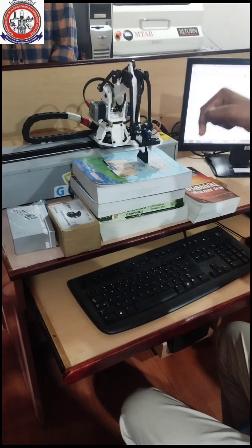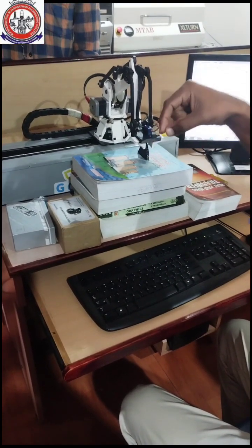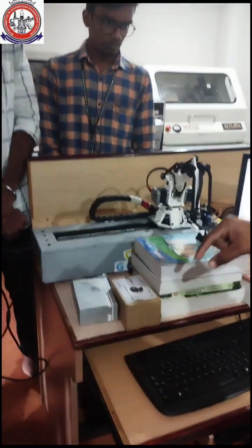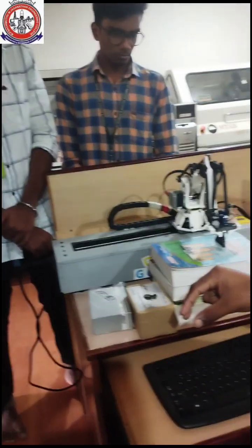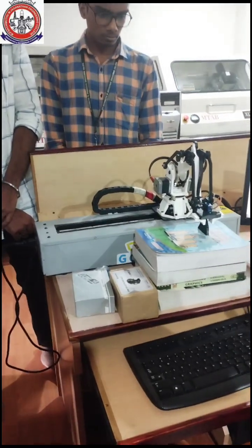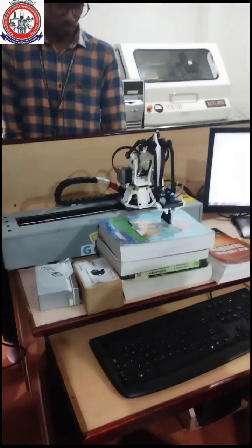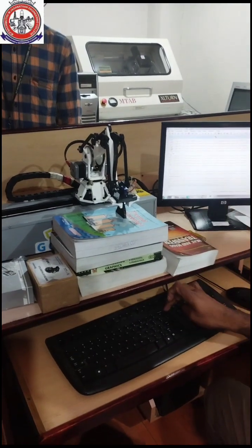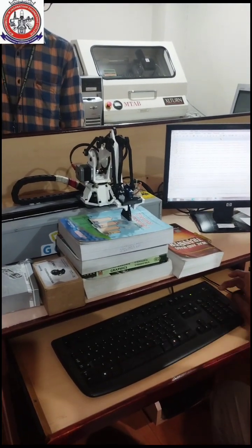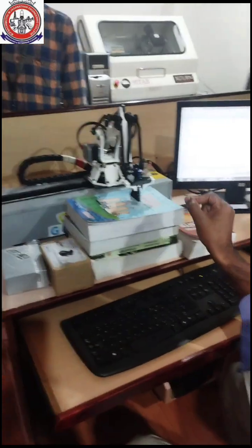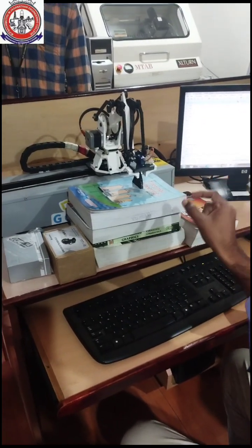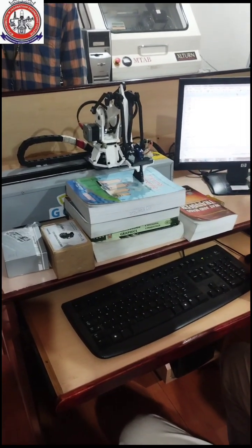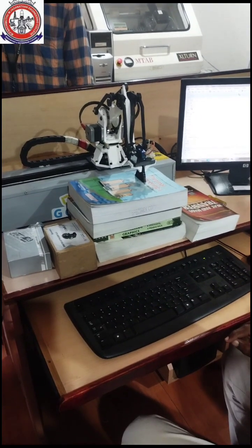Now this robot is ready to pick the workpiece, but it does not hold it yet. Only the gripper position is correct in our setting positions. Now the text command, it will remove M5. M5 is the gripper closed. The fifth axis is the gripper open and close. If you give M5 and press enter, the workpiece will be held.